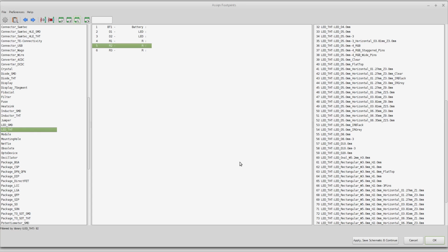What are the characteristics of it? What's the forward voltage drop? What is the internal resistance? What is the gate voltage on the MOSFET? What's what? All the way down the road. What are the things you need to know for a real circuit to get this thing to operate?